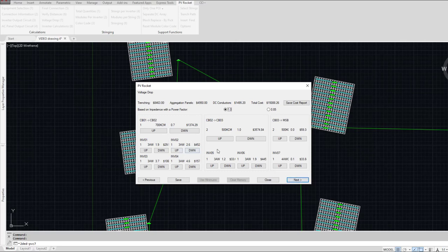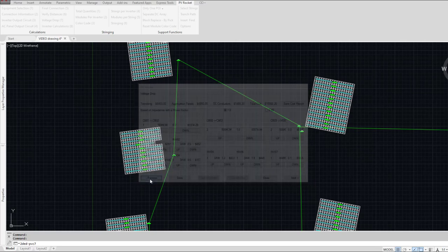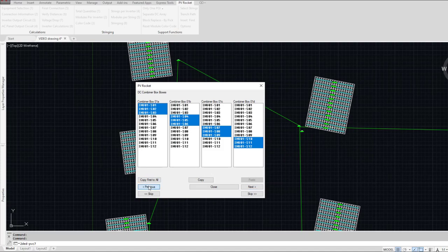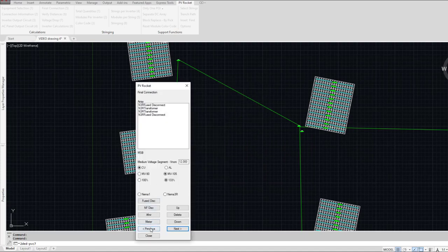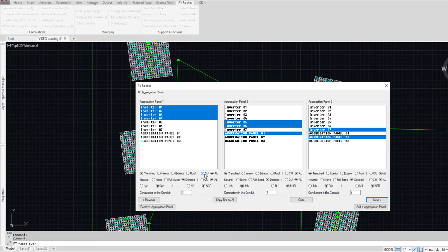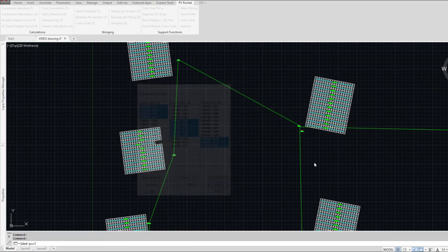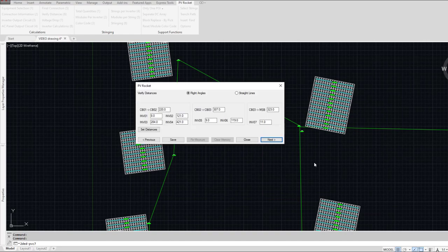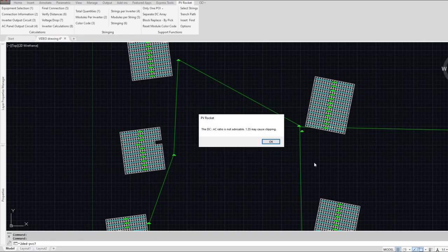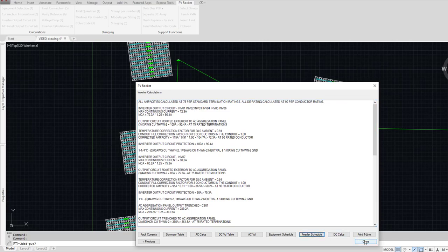Now, I want to talk about parallel feeders, and to do that, I've prepared the system for copper, and these main feeders are aluminum. So let's go back and redo our calcs at copper. I'm going to click copper right there and copy first to all and take copper through. And now I've got a copper system. And let's go to the end and print a new feeder schedule.